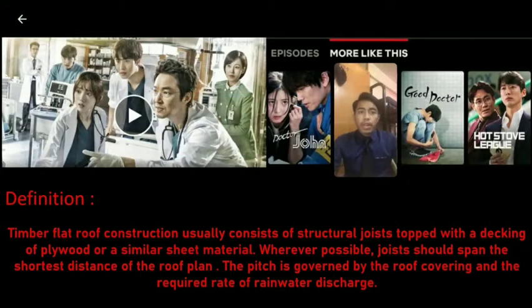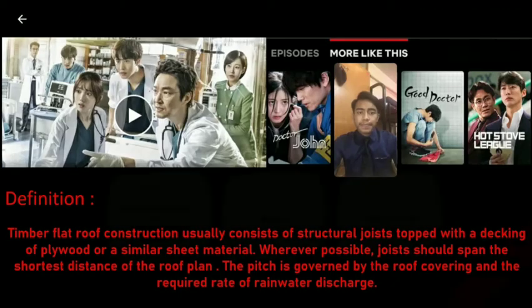Definition. Timber flat roof construction usually consists of structural joists topped with a decking of plywood or a similar sheet material. Wherever possible, joists should span the shortest distance of the roof plane. The pitch is governed by the roof covering and the required rate of rainwater discharge.